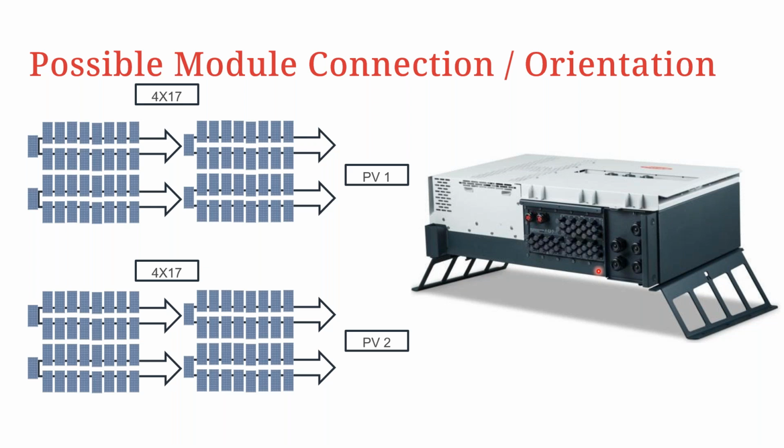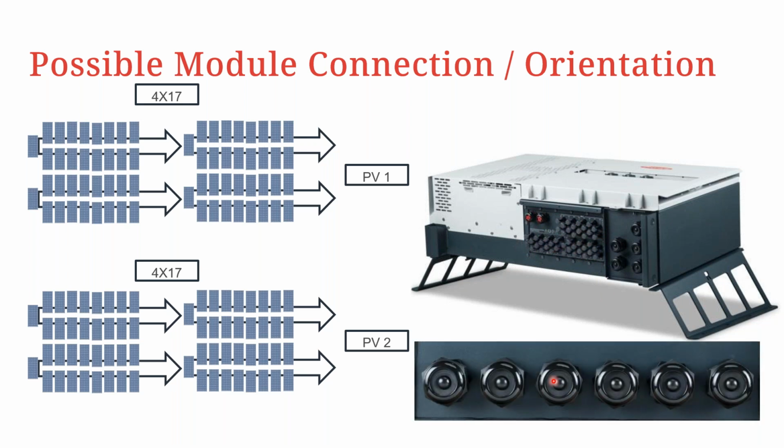So there's quite a bit of flexibility depending on if you're using, for example, the direct version of the Tauro, which already has integrated MC4 plugs, or if you want to, like we said, with a centralized design topology, pre-combine your strings. Then you also have the flexibility with the Tauro inverters to order a pre-combined Tauro configuration that allows you to connect up to 4 DC cables into the inverter.